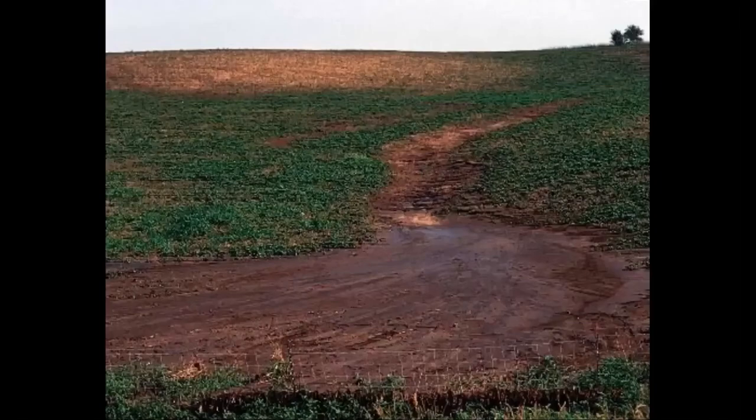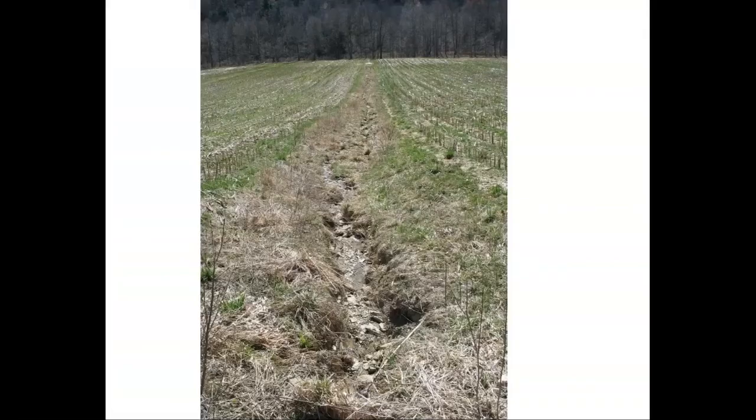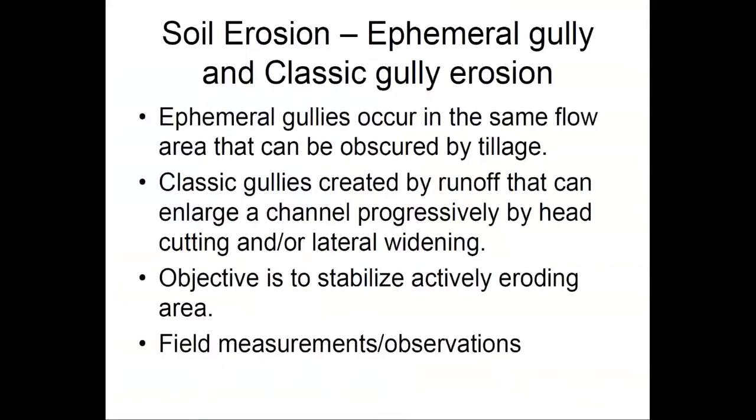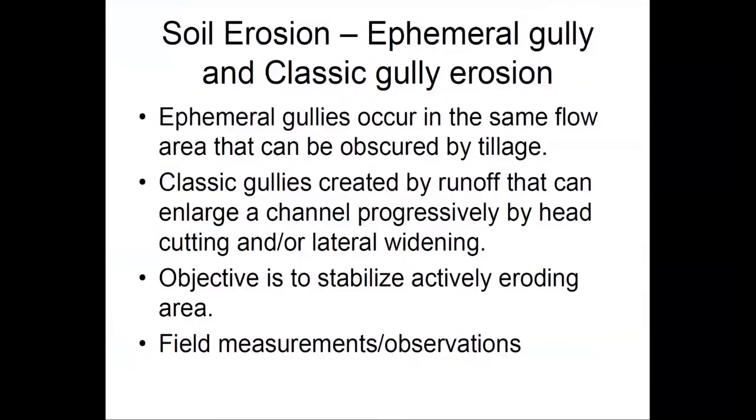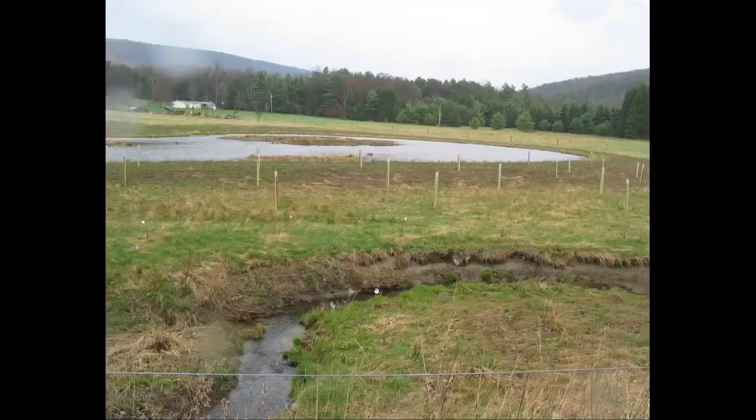Here's another issue: soil erosion, ephemeral gully, and classic gully. So again, the definition of ephemeral and classic gullies. Your objective is to stabilize actively eroding areas. And for your field measurements and observations, you go out there and you measure your gullies: how deep, how wide, how long. That tells you how much erosion you have, and your objective is to stabilize that.